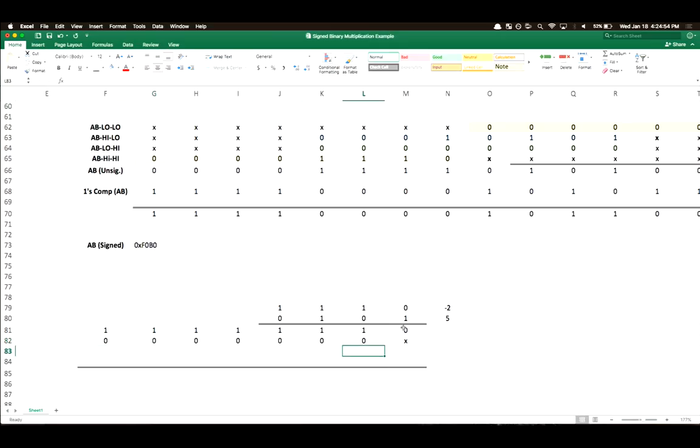Yeah, so this is an alternate method. Since we had a 1 here, we're going to write 1 ANDed with all these. So we got 0, 1 AND with that. 1 AND with 1, we got that. 1 AND with 1, we got that. This one and that one, we got 1. But now you need to do a sign extension. To sign extend it to fill out a whole byte, because our 4 bits times 4 bits is going to give us 8 bits, we need to sign extend. So that's what we did here.